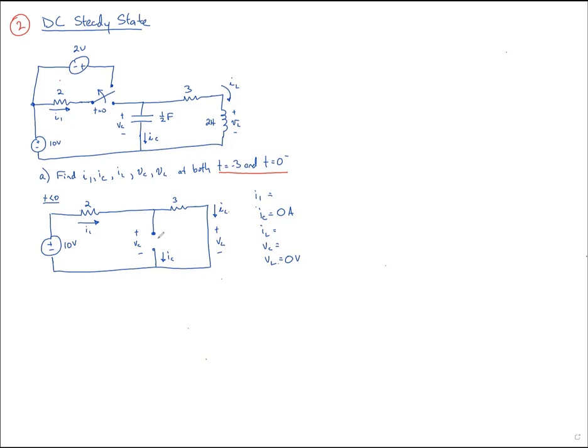And now I think it's clear that V sub C, the voltage between this point and this point, is the same as between this point and this point, right? Because it's connected by a wire, there's no difference, which is the same as the voltage across there, it's connected by a wire, which is the same as the voltage across there. In other words, if we just take V sub C and rotate it sideways, we get V sub C. We just move this negative corner right around the wire, and we move this positive corner right around the wire until it's across the 3.